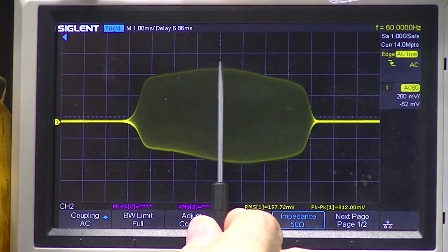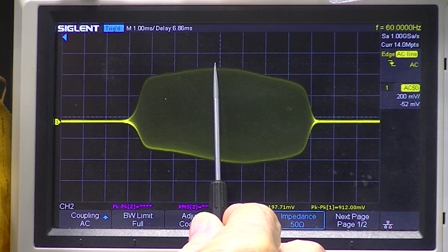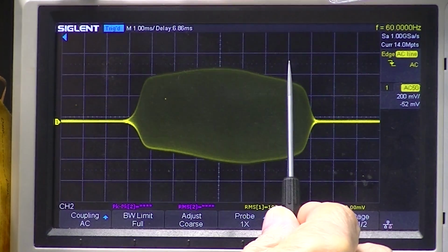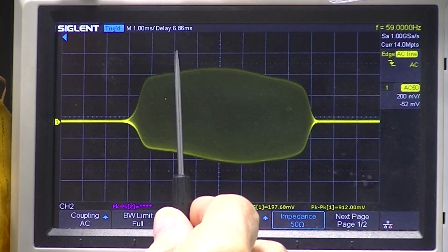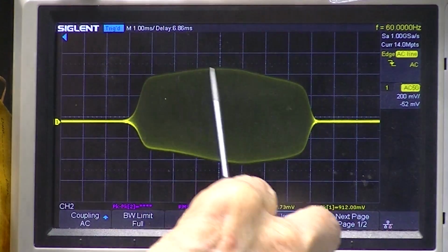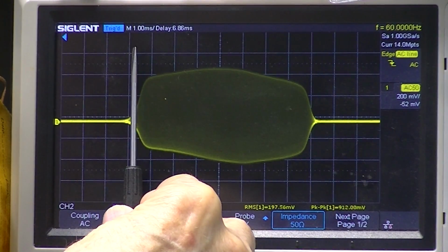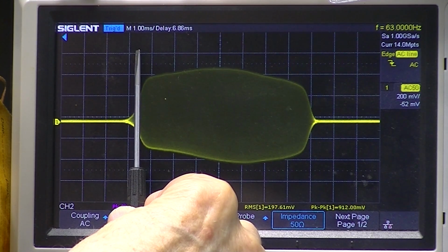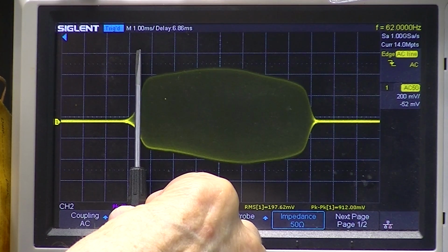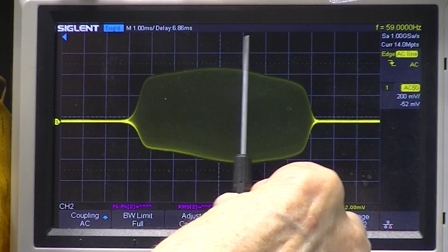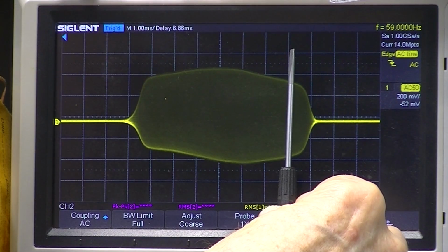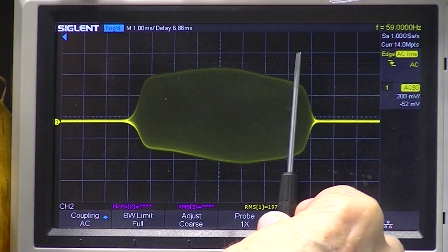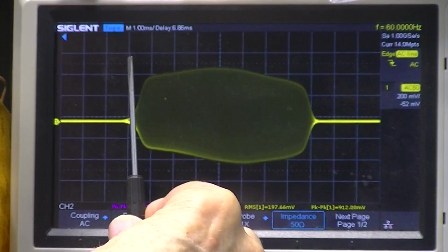In other words, this center is 10.7 megahertz. This is probably a megahertz less, and this is probably a megahertz more. In other words, the frequency inside this envelope starts at some low frequency, say 9.5 megahertz, 9.7 megahertz. And within the envelope, it sweeps up until it gets to 11.7 megahertz. Every burst comes with a sweeping frequency inside of it.